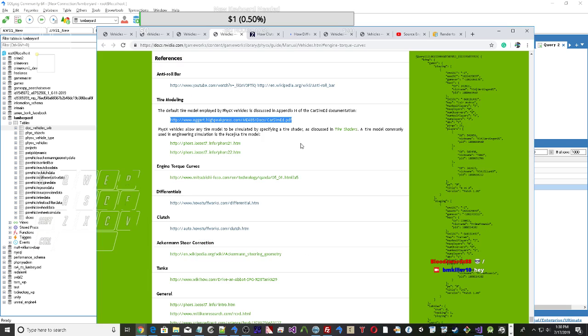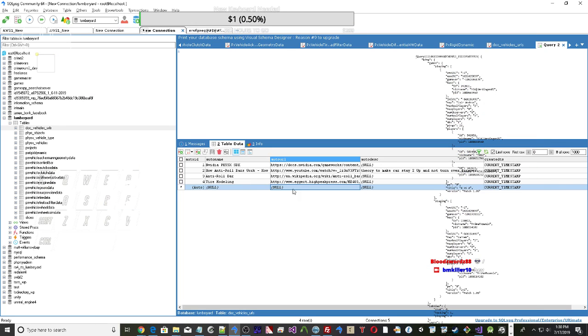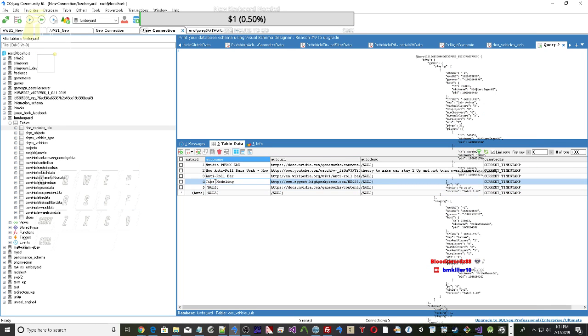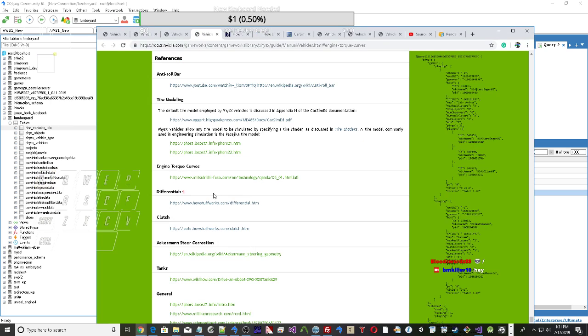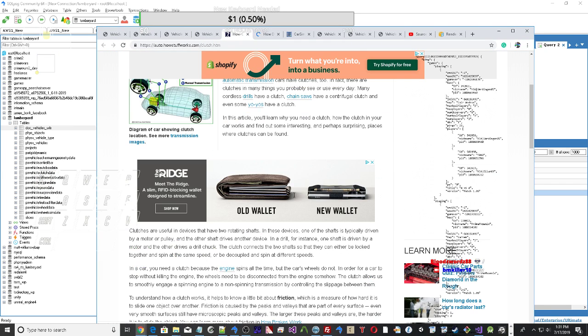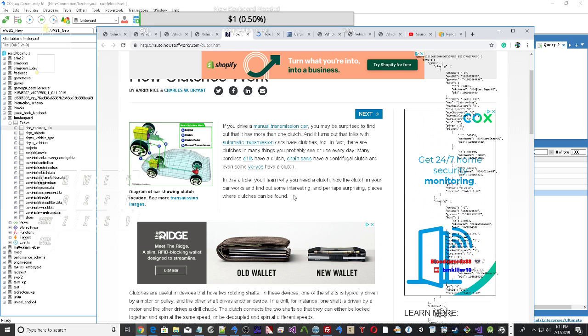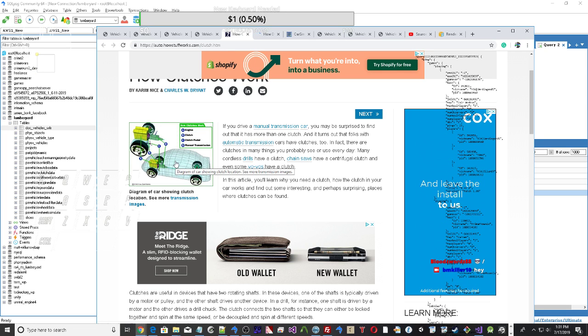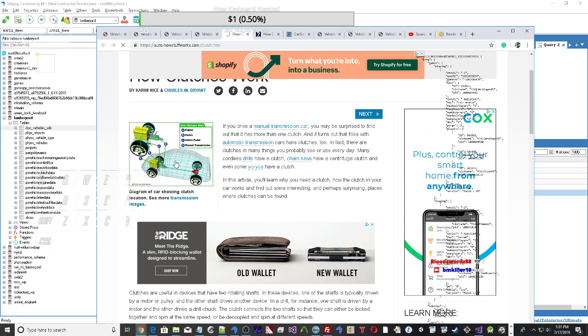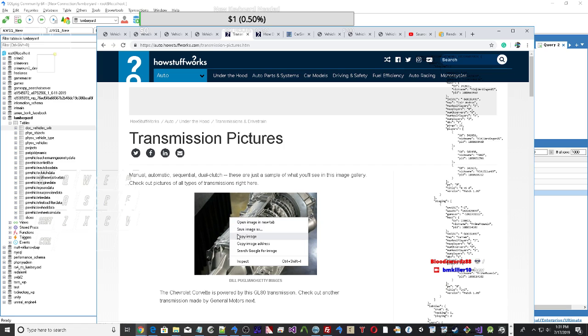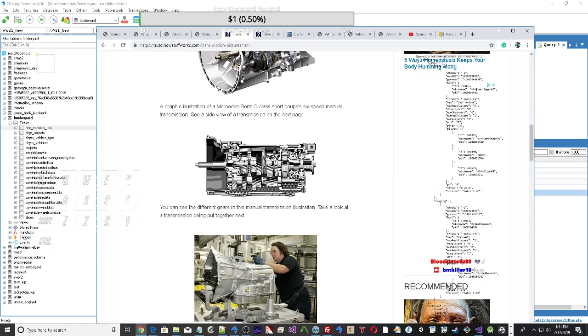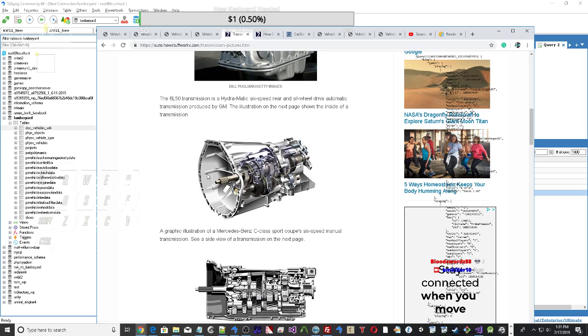Setup wheel simulation data. The following code, taken from Snippet Vehicle 4W, instantiates a PxVehicleWheelsSimData. void setupWheelSimulationData(const PxF32 wheelMass, const PxF32 wheelMOI, const PxF32 wheelRadius, const PxF32 wheelWidth, const PxU32 numWheels, const PxVec3* wheelCenterActorOffsets, const PxVec3& chassisOffset, const PxF32 chassisMass, PxVehicleWheelsSimData* wheelSimData).